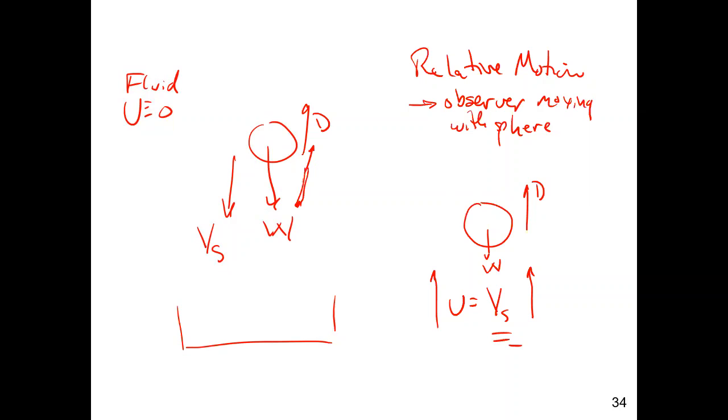So how do we use this, for example, for you environmentals or any of you engineers who are doing construction site erosion and sediment control? You have a fluid coming in with sediment. And so let's say it's entering this sedimentation basin. So this is just a big tank of water. And you've got some discharge in, and you've got some cross-sectional area of this tank. And again, this could just be an excavation in the ground, but the horizontal velocity is Q over A. That's an equation you might have heard of called continuity.